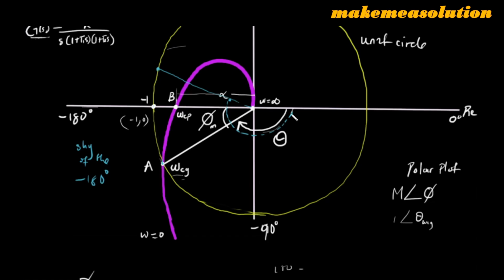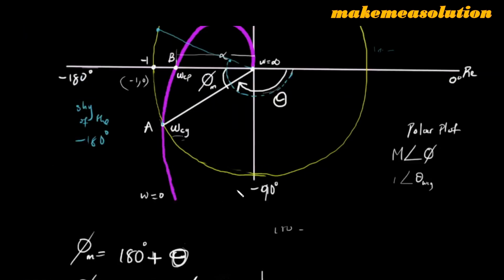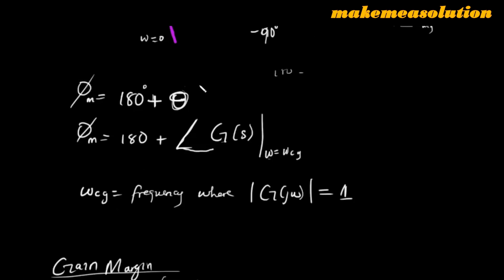So anytime that the theta is bigger, it will now drive A above. So when you calculate 180 minus something bigger than 180, it's going to give you a negative value, and that means the system is unstable. The summary of what I'm trying to say is that for our system to be stable, the magnitude of theta, irrespective of the fact that it's negative, must be less than 180, or the phase margin must be positive. So when you do 180 plus this angle, it must be positive. In other words, it must be greater than 0.